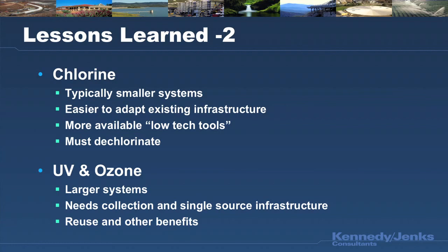as opposed to UV and ozone, because they're so expensive, you want to use larger systems for this technology. Chlorine is much easier to adapt to existing infrastructure. There's more available low-tech tools. So if you go to your catalogs, there are pellet ways to add chlorine via pellet methodologies, pellet ways to neutralize the chlorine in place.